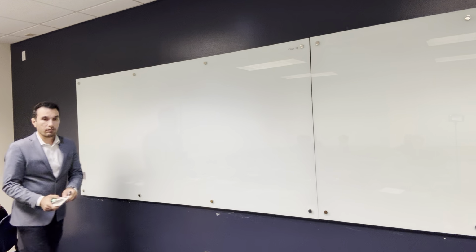First you get reactions, and then get the bending moment for the original beam. And then second, remove the original load and put a unit load at the point that I'm asking you to get the deflection at. If I'm asking at the middle, you put a unit load in the middle. If I'm asking here, you put a unit load here. So if at the middle, you remove all the loads and you put a load Q equal to 1 here, right?